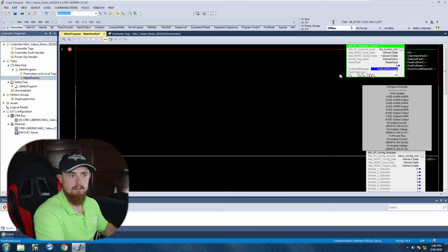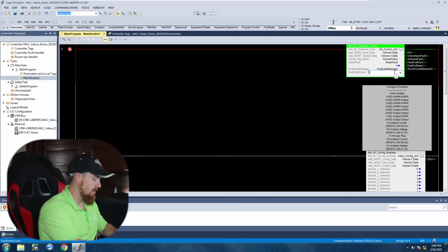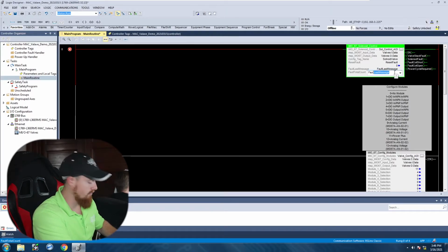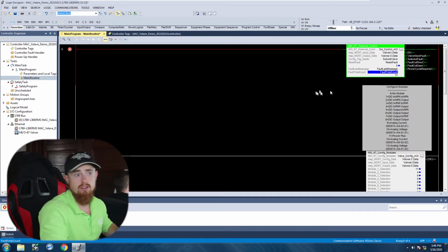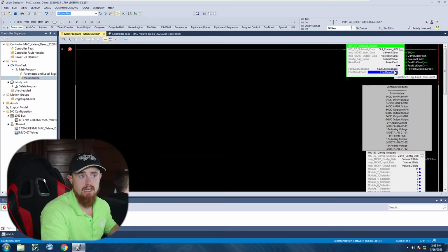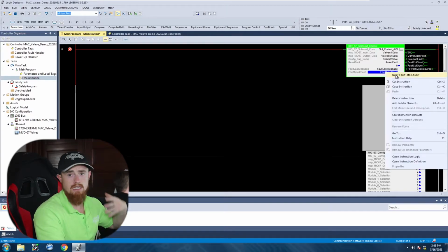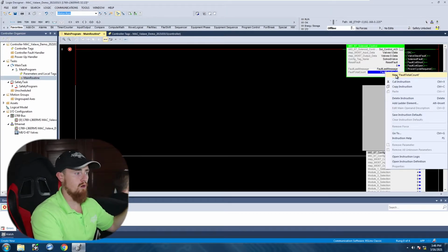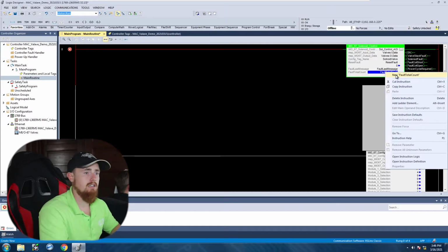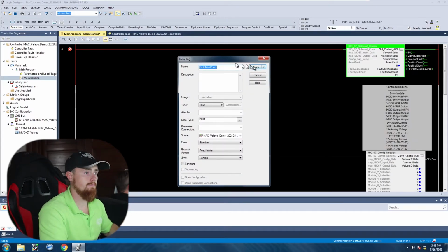So we'll create that. We're just going to repeat this one again. I'm just kind of going through and repeating these for the sake of making the video quicker. To be honest, if we were doing an actual application, I probably would go ahead and create a UDT. Sometimes I'll get halfway through configuring something like this, and then I'll decide, you know what, I think we are going to make this a UDT. Anything that I think will make our programming more uniform and more patternized, we'll take the extra initiative to do so. I just want to point out that all these have different data types.